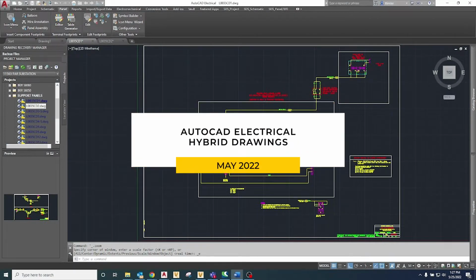In the last video, I demonstrated two different methods of approaching the conversion of AutoCAD drawings into AutoCAD Electrical designs. In this video, I want to continue that AutoCAD Electrical conversion discussion with the use of a tool in the SDS Toolkit. In some cases, the best approach to converting some AutoCAD drawings is to create a hybrid AutoCAD Electrical drawing. A hybrid drawing is defined by me as an AutoCAD Electrical drawing that is designed to be both a schematic diagram and a wiring diagram.